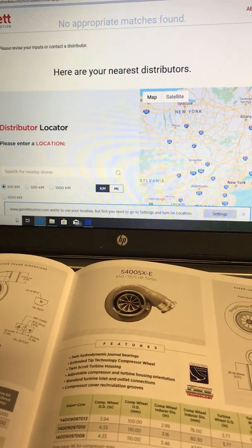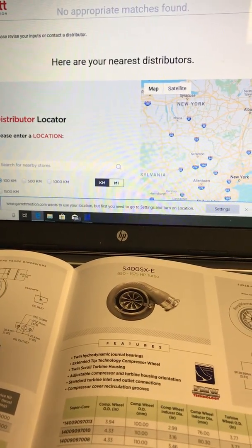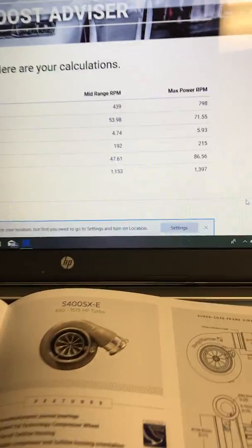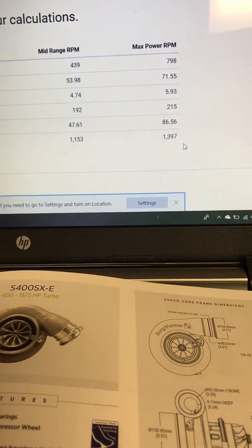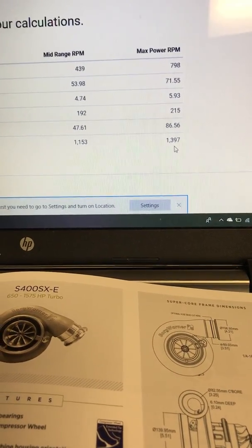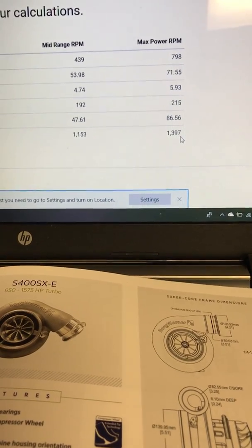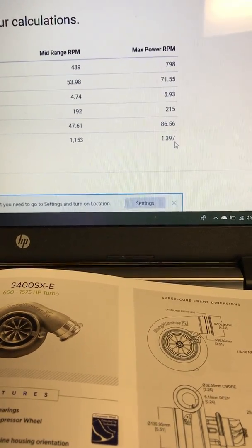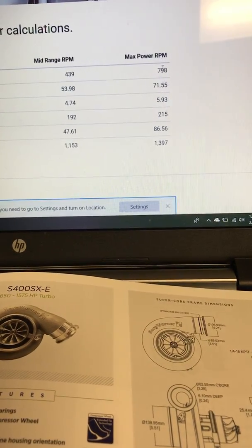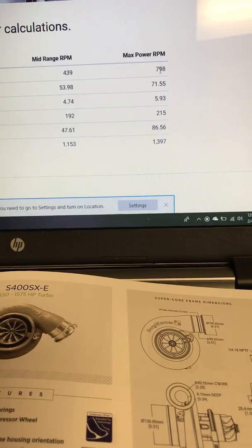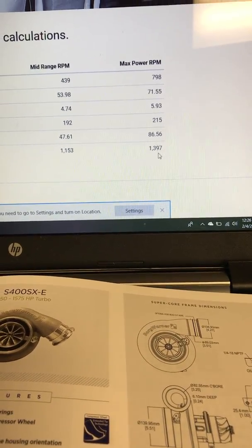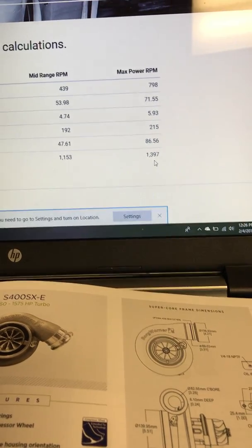And the other thing that does is, look at the torque. To get 800 horsepower, 798 at only 3,000, you have to have almost 1,400 pounds of torque. That's hard on everything. It's hard on clutches, hard on transmissions, hard on rears. It's killer. If you take this number, keep it the same, but raise that RPM up to 4,000, these numbers go way down, because torque and horsepower are nothing but math.